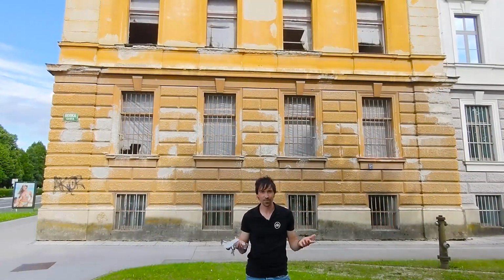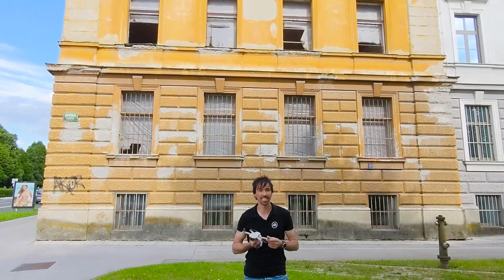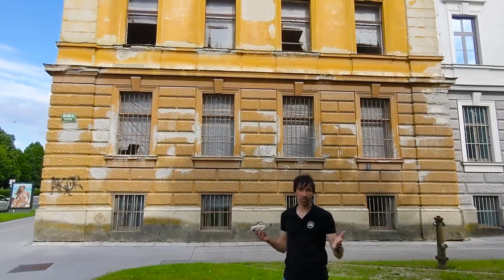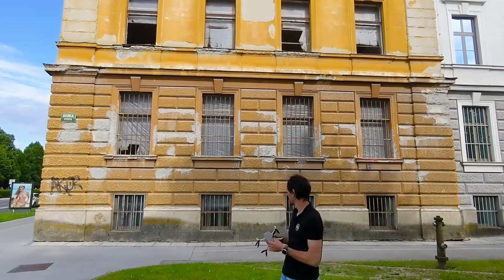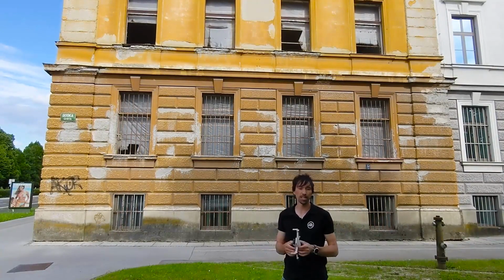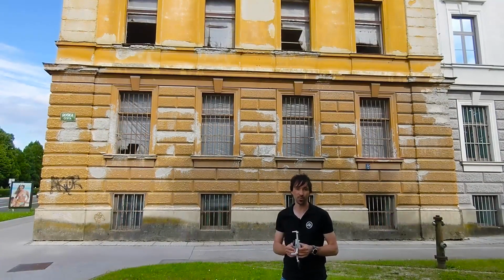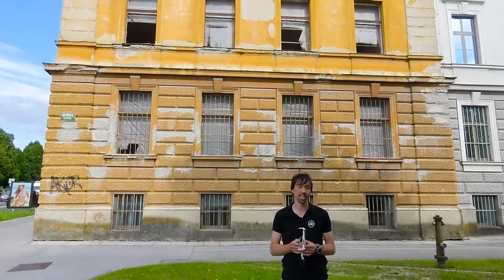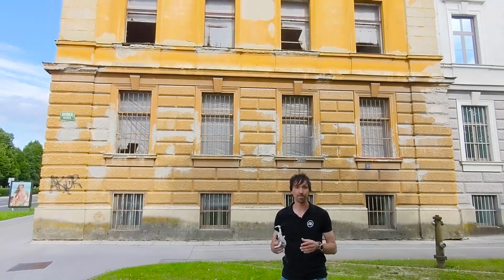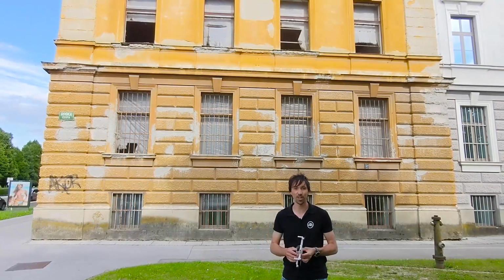Okay, I finished with my field work. It was a 1 battery flight, approximately 60 images for this building facade, and I used the measuring tape to measure 2 distances between windows, which will help me to orientate the model and get accurate dimensions between specific objects we need to deliver to our end customer. Let's get back into the office, import the images, and create a stunning 3D model.